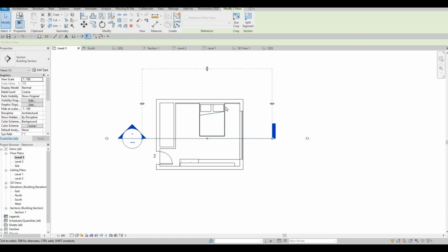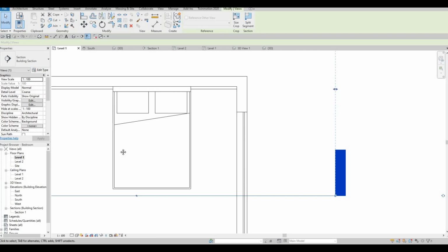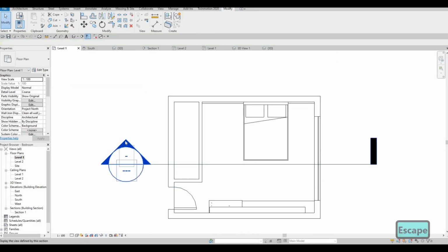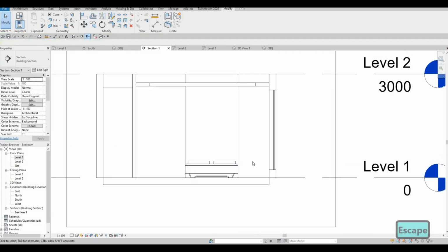And here we're gonna add in the side table. So we're gonna add a side table. So double click here, and then let's design this one. So I'm back with the section, and as we know, we flip it, and then now we're gonna add in some side table.